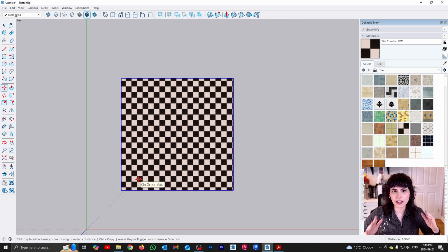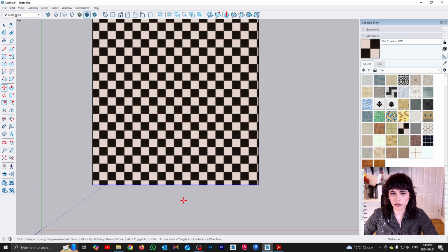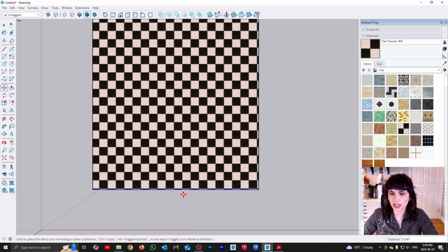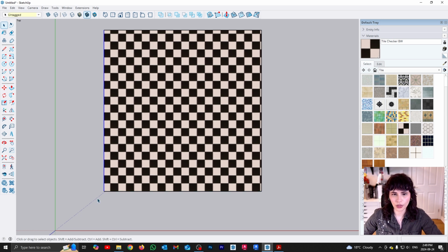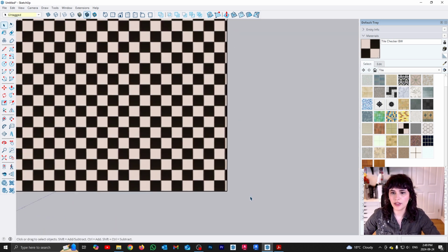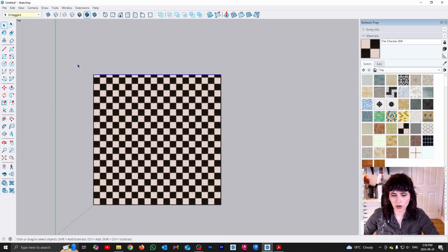The position of my texture is locked to the geometry, and therefore when I move the geometry, the texture goes along with it. But if you're working with raw geometry where you can select individual lines or faces, check it out. You can move the position of the lines, so you can deform the geometry, and that will not move the texture. So what I can do here is just move my lines so they create a better alignment. Let's say here, this one here, and then do the same thing on this side. There you go.